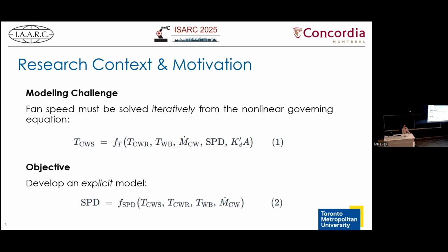Funny enough, what we usually do is push our cooling towers down. They have VFDs, we run them as efficiently as possible. And then we wind up spending more on our chillers. So we're saving pennies on the cooling tower to spend dollars on our chillers, which doesn't make any sense. But we wanted to figure out how much energy we would actually save if we push the cooling towers to the maximum to be gentler to the chillers.